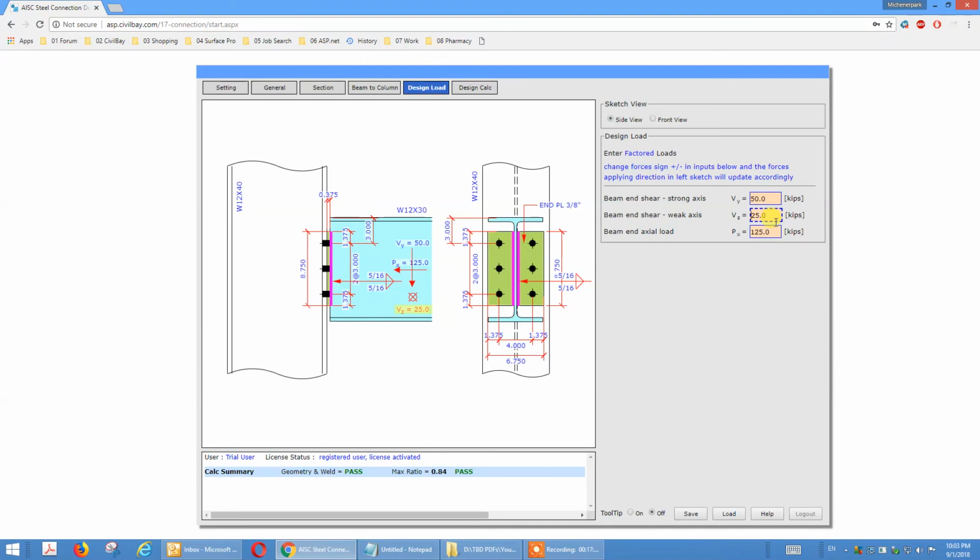Normally we don't get these shear connections to take the shear force in the weak axis. But the project lead insisted on assigning these shear connections with that capacity, which gave the steel fabricator a tough time to accommodate it. We normally get the horizontal brace to take all the shear in the weak axis. The shear connection only takes the strong axis shear.